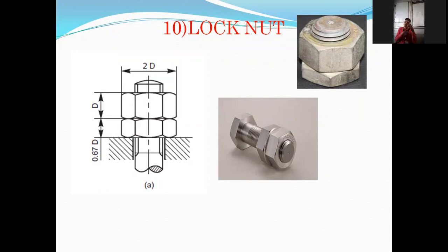One nut we have taken, suppose, on that we have fixed another. We have taken one bolt on which we have to fit one nut. Further, one more nut we have to fit. After that, once they are going to touch each other, we have to rotate in opposite direction, so that it will get fit.